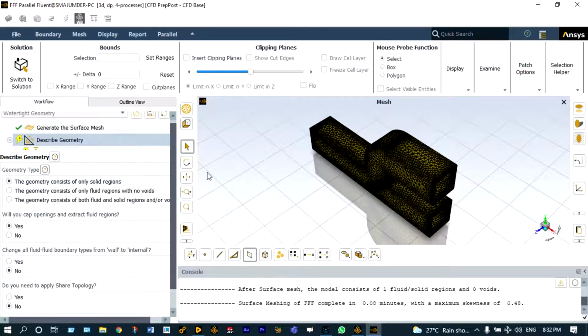That means we have only one solid geometry here. We didn't provide any kind of fluid region. So it is showing that the geometry contains only one solid region. Second one, do we cap openings and extract fluid regions? Yes, definitely. And the next one, change all fluid boundary types from wall to internal? No.